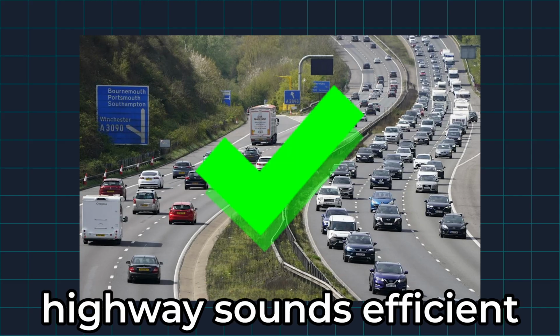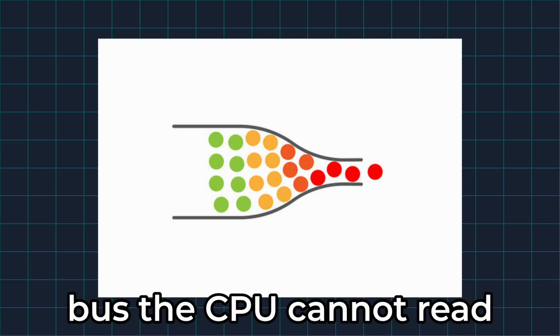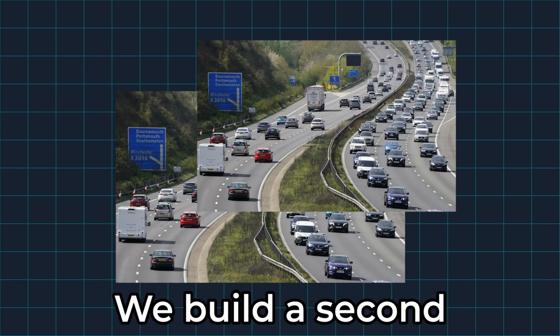Now, sharing a single highway sounds efficient, but it leads to a massive problem known as the von Neumann bottleneck. Because there's only one bus, the CPU cannot read an instruction and read or write data at the exact same time. The CPU ends up sitting idle, waiting for memory access. So how do we fix the traffic jam? We build a second highway.